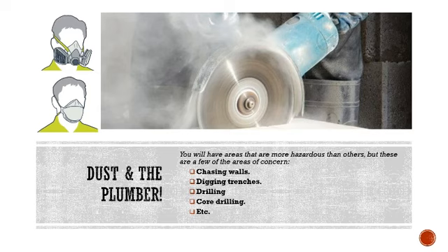So this is a constructed building. We're already inside a kitchen, we're inside a bathroom. They're generally not very large areas. And now we are having to take our power tool out and start chasing a wall in order to put the plumbing inside. Or if you need to put lagging on some of your piping, then you need to cut quite deep into the actual brickwork or concrete work in order to place your piping inside.